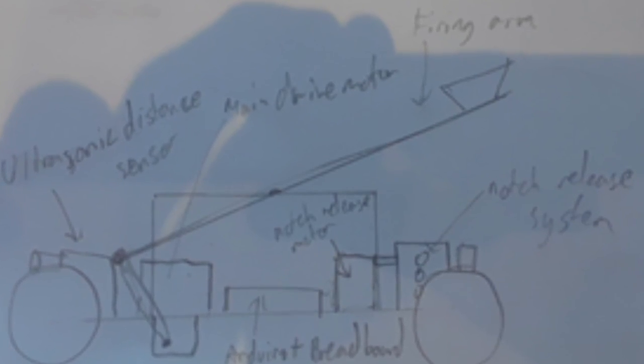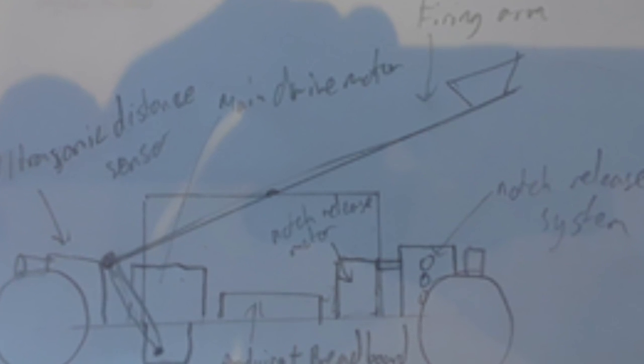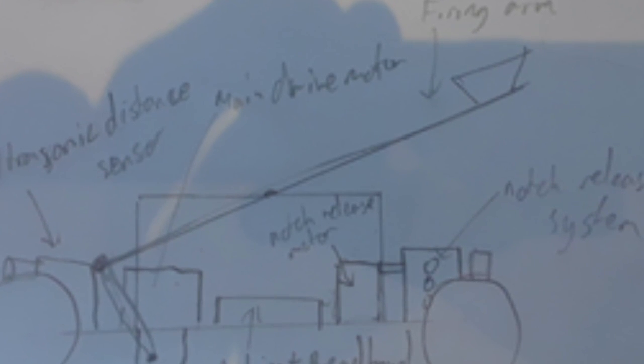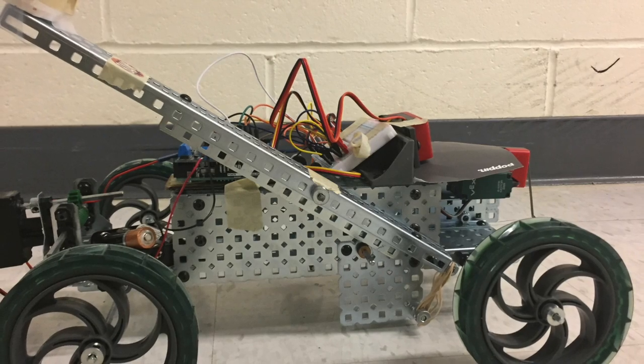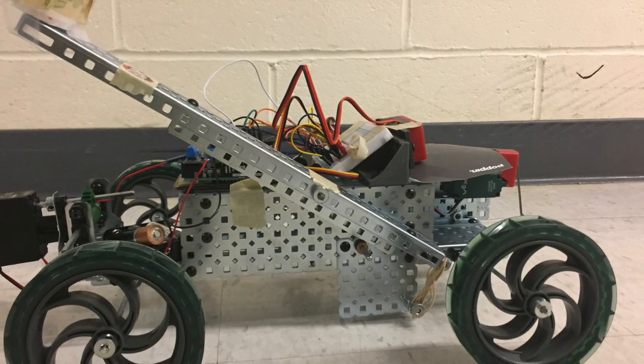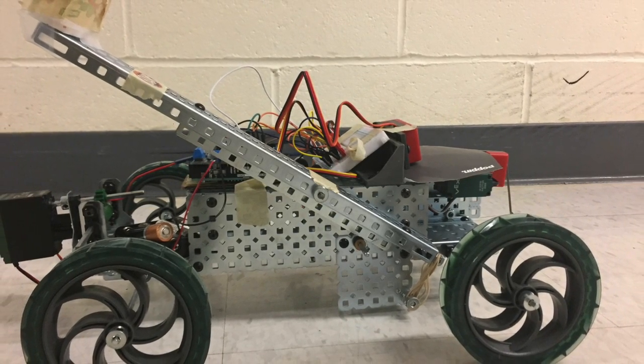The joystick is fairly unique. We used a pin release mechanism, but using a motor which controls rotary motion, the first gear, that converts to linear motion, which is the worm gear. So yeah, it was a fairly unique design. We didn't see it in many other projects.